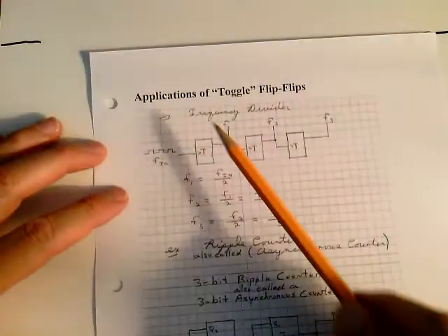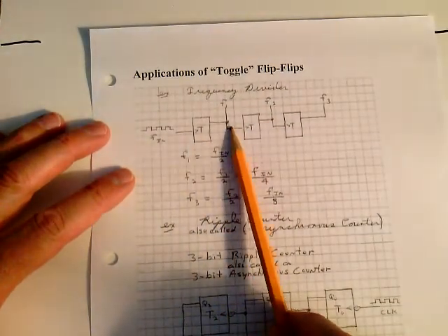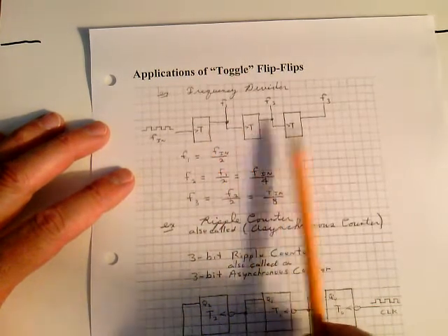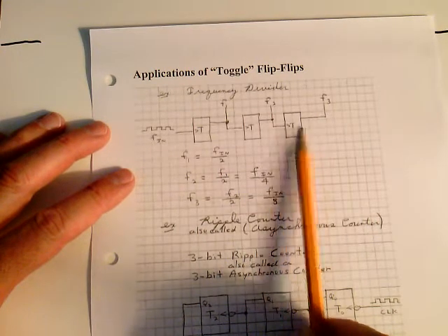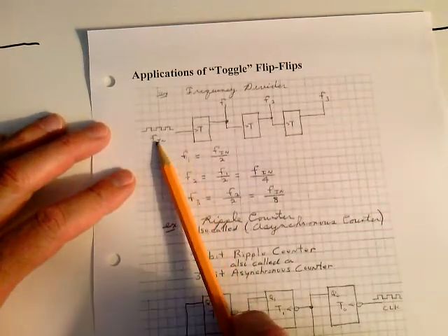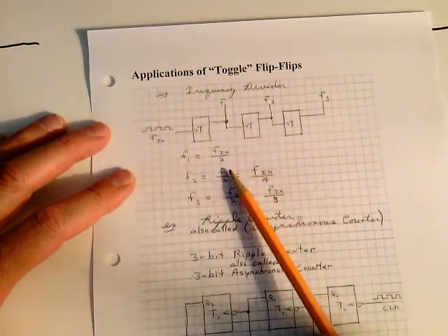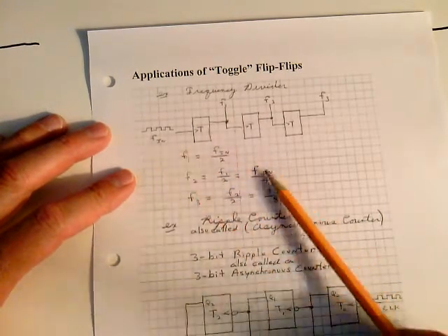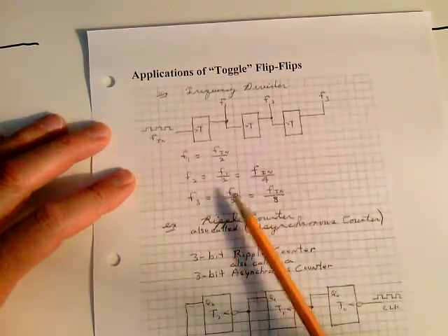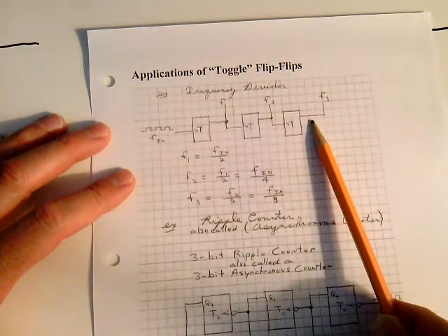Look on page 162. For more applications, frequency divider, already talked about it. Here you have frequency in. Here you have a toggle flip-flop, positive edge triggered. Here's your output. The output goes to another input of a T flip-flop. And you could build these circuits. You know what's inside here now. The output of the second one here goes to the toggle flip-flop number 3. So frequency 1 here is frequency in divided by 2. Frequency 2 out here is frequency 1 divided by 2, which is frequency in divided by 4. Frequency 3 out here is frequency 2 divided by 2, which is equal to frequency in divided by 8. So it's powers of 2.